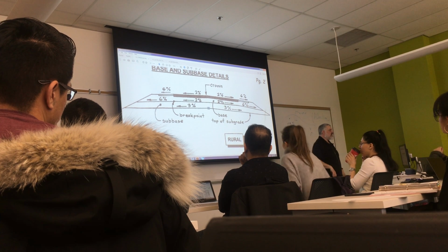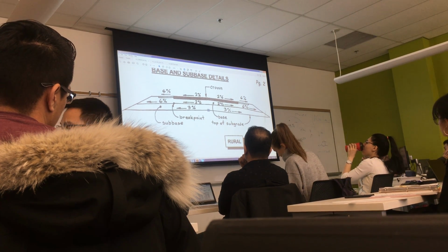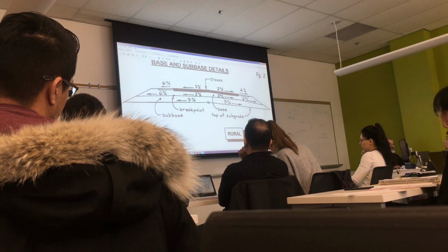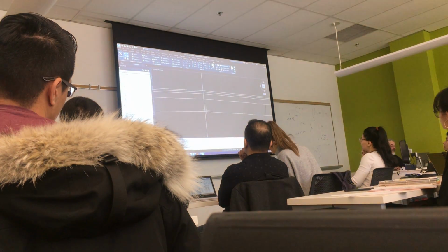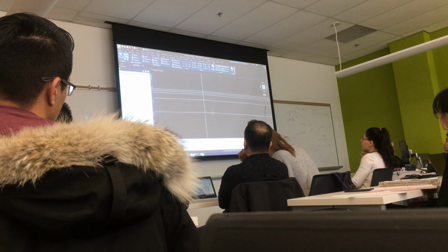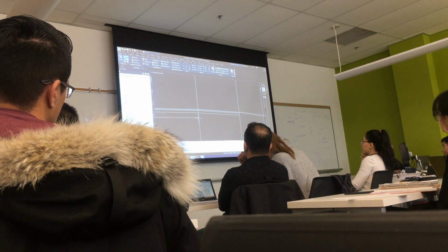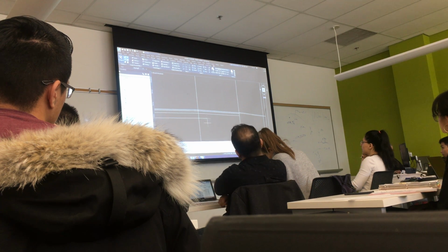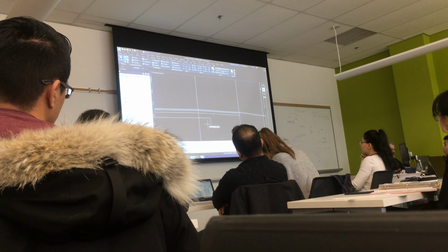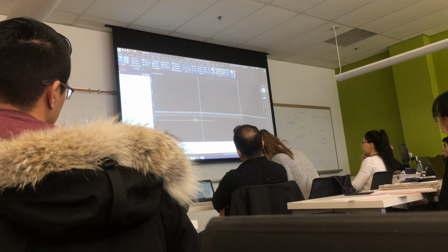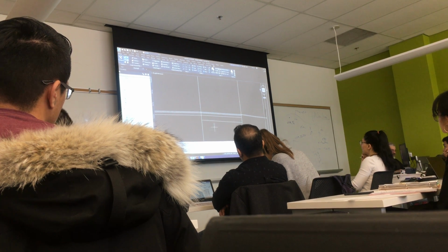We may get slightly thicker layers. So I have to establish 3%. So I've got the crown of the subgrade in the right spot, but the slopes are wrong. Go back to CAD. So that elevation's good, but it's the wrong slope. So now I'm going to get rid of this. I'm going to draw a line from here. Cross 1. 3% is 0.03. Close it. There's the angle I'm looking for. I'm going to delete that. I can get rid of this now. Extend to here. Mirror.